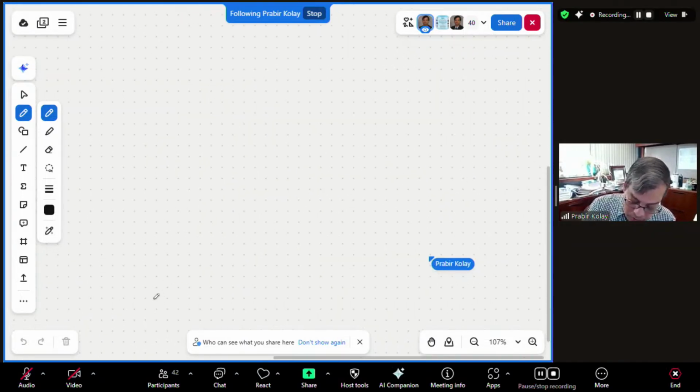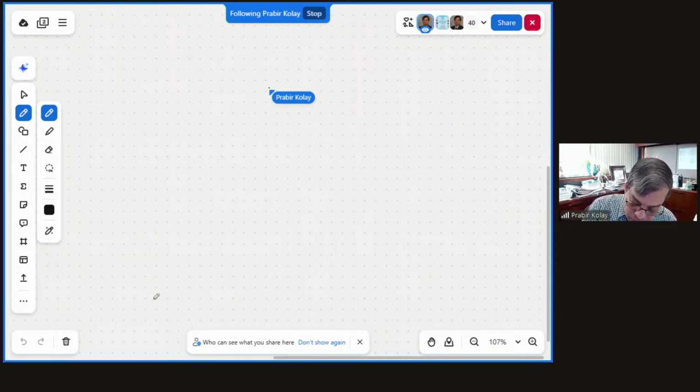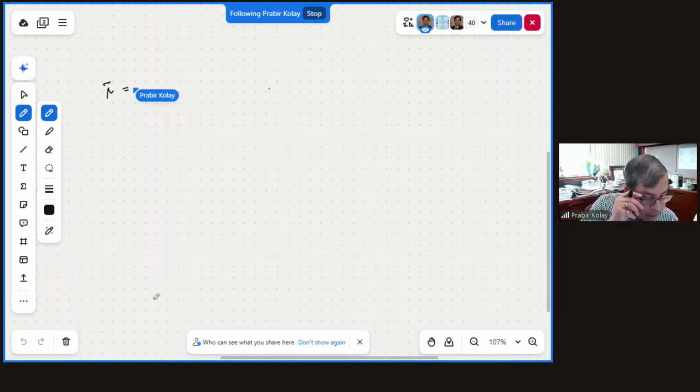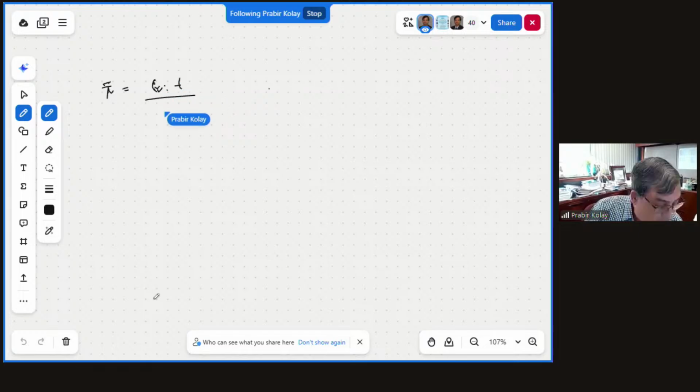Tv now, again you need to use the same equation. Tv is equal to Cv times t divided by the height of drainage, H whole square. Can you read it really?